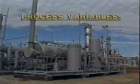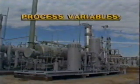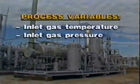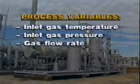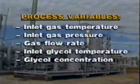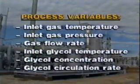Now, several process variables determine the degree of water removal in any glycol dehydration unit. The variables which affect the unit's efficiency are inlet gas temperature, inlet gas pressure, gas flow rate, inlet glycol temperature, glycol concentration, and glycol circulation rate.